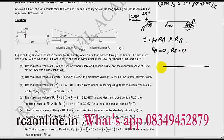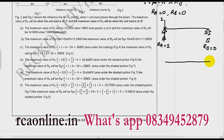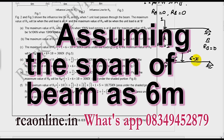Now let us take a second case. When the 1 kilonewton load is at point A, what do I get? RA is equal to 1 and RB is equal to 0. Now let us take another case. When the 1 kilonewton load is at a distance of x from A, what will be the distance from B? It will be 6 minus x.